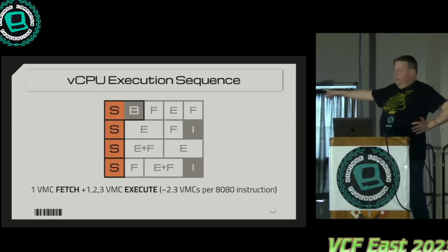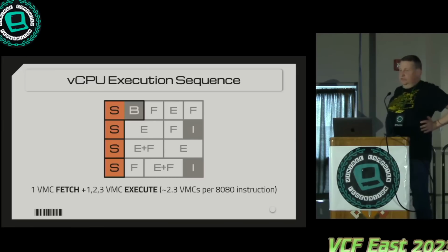But the next instruction I fetch is a double cycle one, so that takes 2. Then I fetch, and I get maybe another 2 cycle one. So that has to skip to the next line. So it inserts an idle cycle. So it can't execute 2, it'll miss the sync pulse. So it has to just kind of burn that.